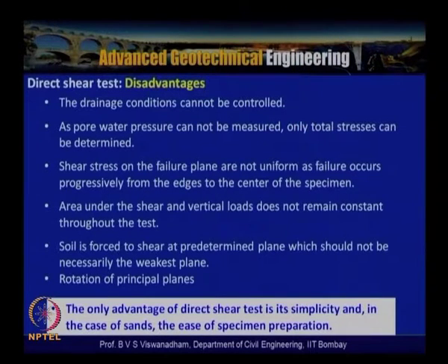So after having discussed the direct shear test, first of all, the direct shear test is a simple test and actually allows us to determine the strength parameters of soil very easily. The failure plane is one to be noticed: the failure plane is predetermined and it is very difficult to control the drainage condition. However, to some extent,